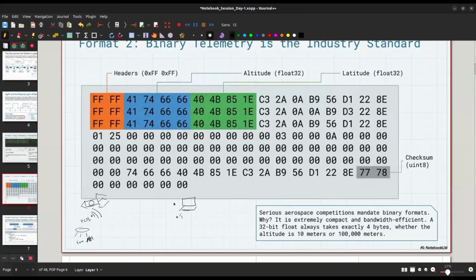In my case, what was happening is in case one, we'll discuss case two later. This is wrong, by the way. What was happening was the GCS was trying to receive the data. It was trying to look out for altitude, then temperature. So it says that if you receive any values, give the first value to altitude, give the second value to temperature. Suppose in the correct case, it sent the value as altitude, comma, temperature, and it was received by the GCS. And by this logic, it decoded the value as altitude equals 23 and temperature equals 30.